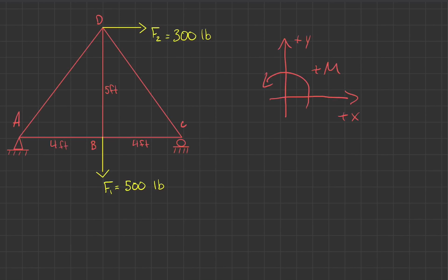Okay, so once we've redrawn our truss and established a coordinate system, our next step is to see if our truss is statically determinate.